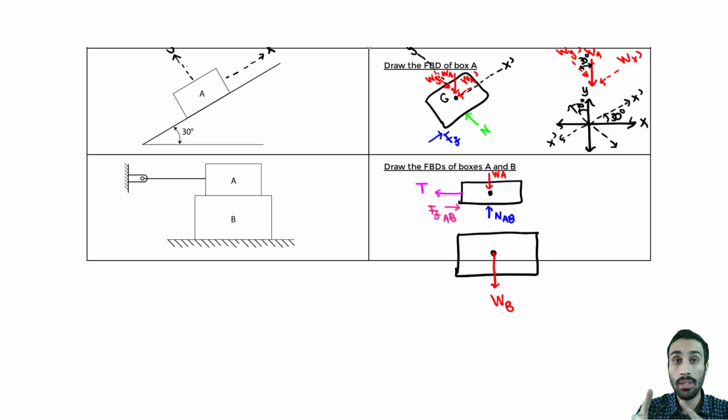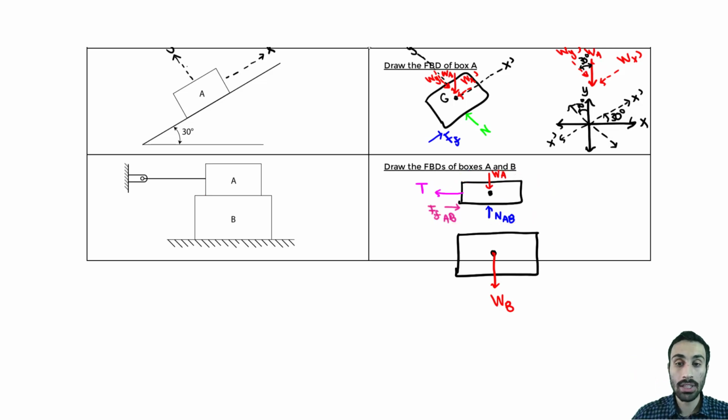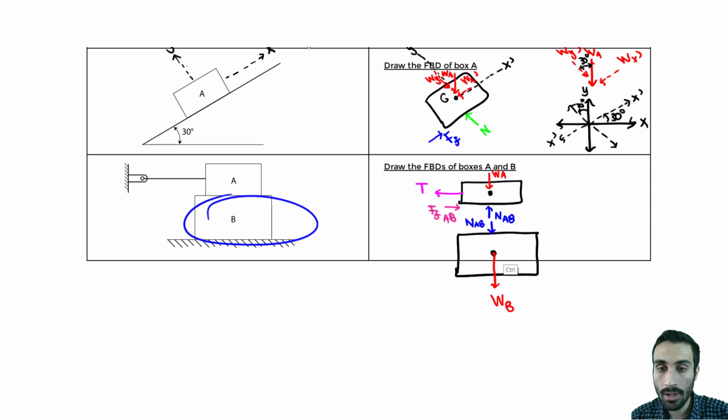If you drew it up again, everything's going to get messed up. The signs get messed up. So in this free body diagram, we drew this normal force going up. In the next free body diagram, which is the one for B, it must go down. So you have to draw it down for this one, and it's the same one. It's the normal AB. It's basically the weight of box A, but I just like to draw it as the normal AB because it's being induced between those two surfaces. It acts on A, but be careful, we drew it up in the free body diagram for A. For the free body diagram for B, you have to draw it down, equal and opposite direction.